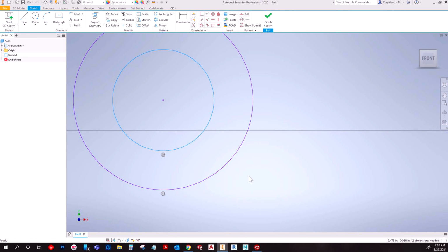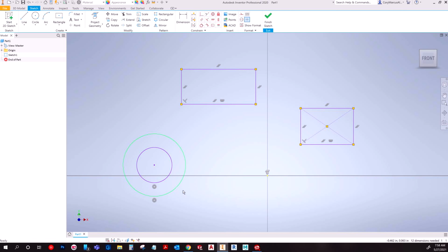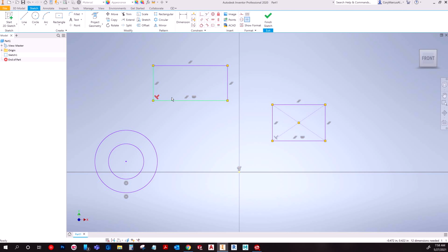And I wouldn't advise, although I've got my constraints on, I actually wouldn't advise working with them visible, because what happens is when you try to tug your geometry, it doesn't let you, on a rectangle in particular. Basically, I pull on the constraints instead. So when you're trying to tug test and it's not working, sure, you can tug here and that's fine, but you're probably going to mess up, because sometimes you may not have your angle position in there.